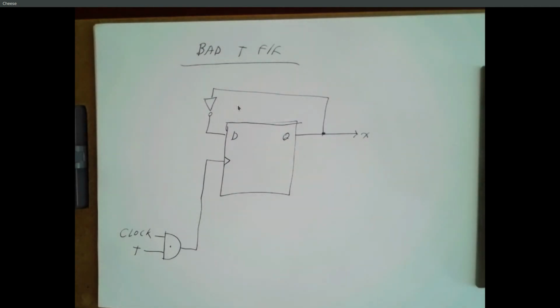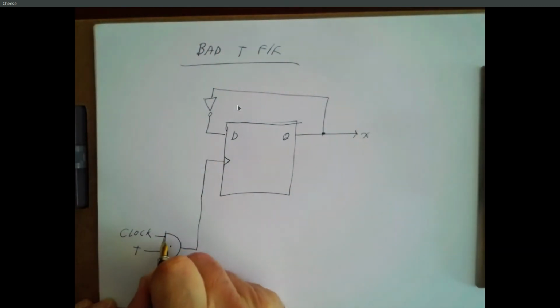The problem with this is you have one clock running in the system. One master clock that's supposed to go everywhere that needs to be clocked. And you try to set it up so that clock hits all of the things being clocked roughly at the same time. There may be little wire length differences, but more or less you want all your flip-flops to respond at the same moment. Except this poor flip-flop over here doesn't respond until this clock passes through this piece of logic.